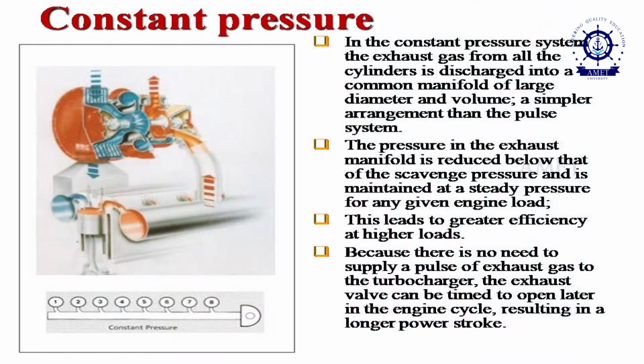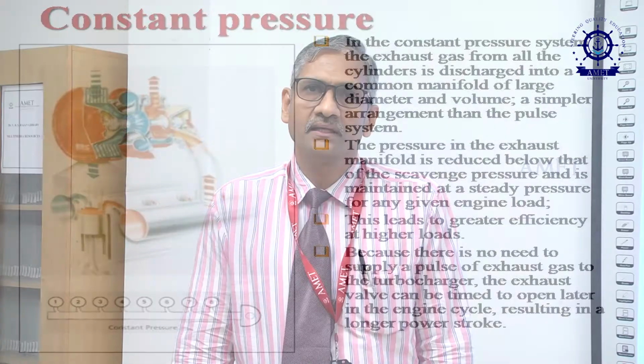So, to avoid that, what we have is the blower, when it is at lower RPM below a certain pressure, it will run continuously. This typical blower is generally an electric blower which is running from an external power source. This blower will then assist and support the engine by supplying air to the unit, and thereby you will find that the unit is receiving enough air and there is good combustion in the unit, and thereby we can avoid the black exhaust gases. So, this is for a main engine.